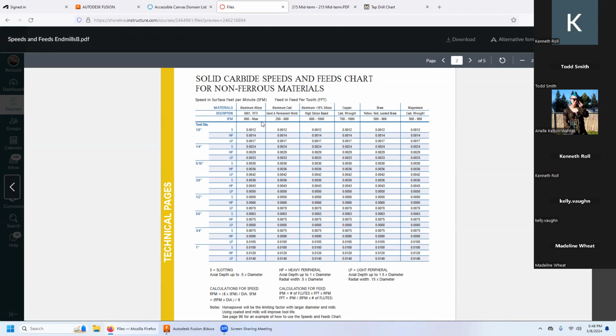Yeah, it's going to affect spindle speed. But what's being maxed out here? The speed. So as fast as your machine can go, that aluminum likes it. So wind it up.